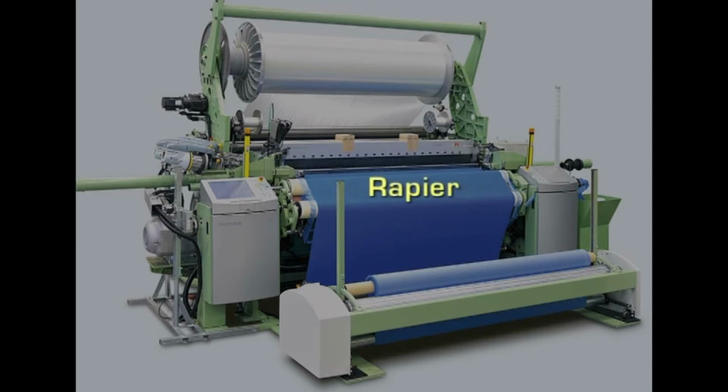Now students, let us learn about the rapier method of weft insertion. In the rapier loom, there is a small needle like rapier which takes the weft yarn from one end to the other. Now in case of different looms, there can be one rapier or two rapier. Now this rapier is a needle like structure that is guided on fixed rods or on flexible belts. This belt passes through the shed and transfers the weft yarn from one end to the other.